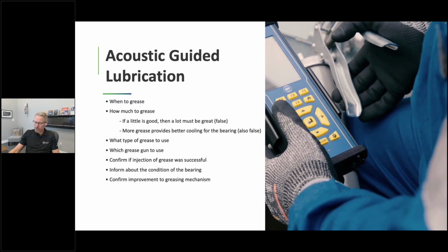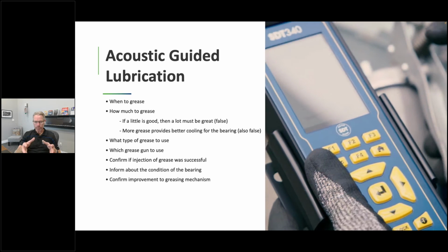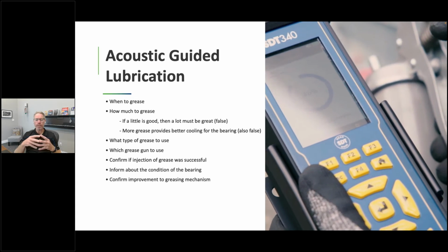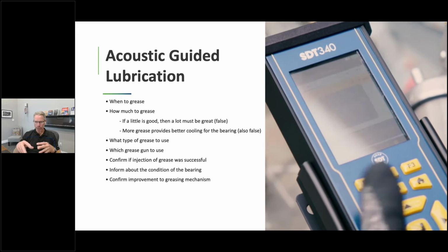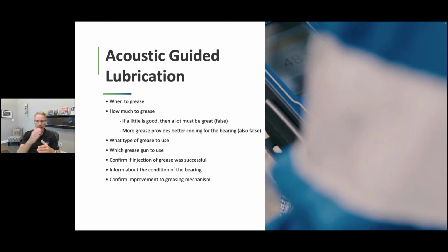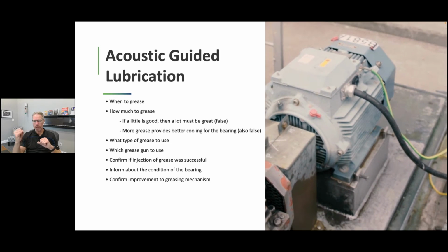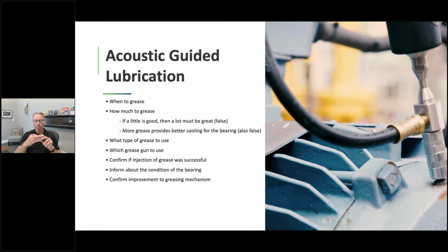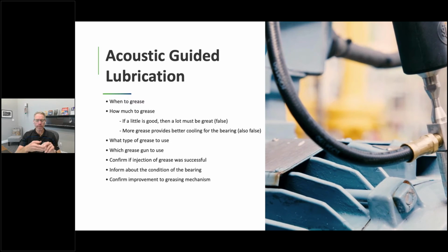Now, when we look at the phases of lubrication, what happens when we inject fresh grease into a bearing? We have to understand that there's churning and bleeding phases of grease replenishment. And those are critical in tying together the role that ultrasound plays in ensuring that we do this right. And by right, I mean a solution that provides guidance at each step of the grease replenishment task. A solution that will tell us when to grease, how much to grease, which type of grease to inject, because we don't want to mix incompatible greases. I'll talk about that in a second.